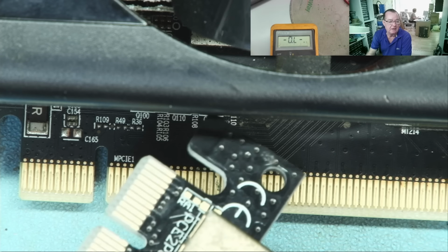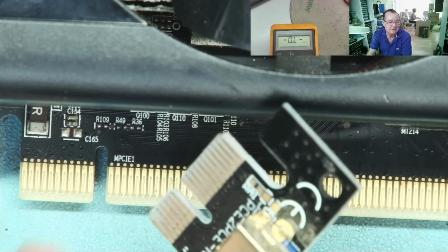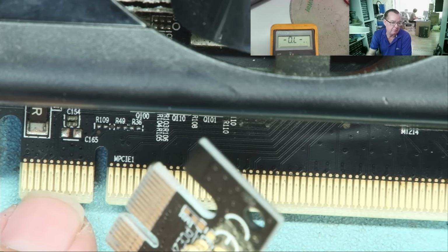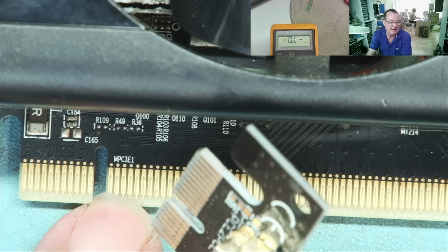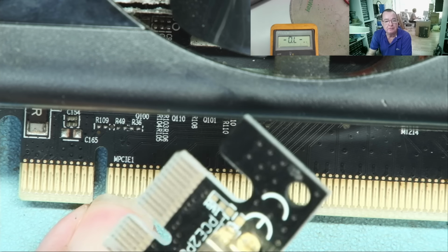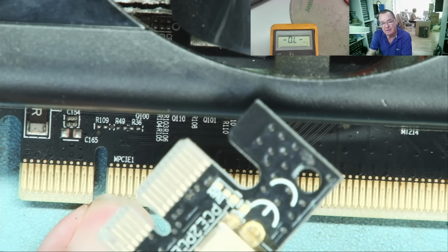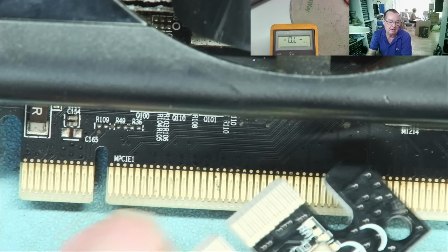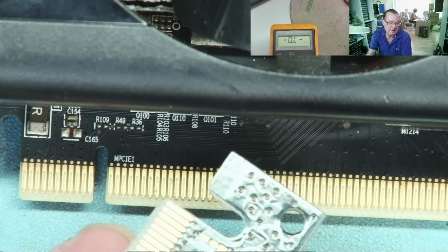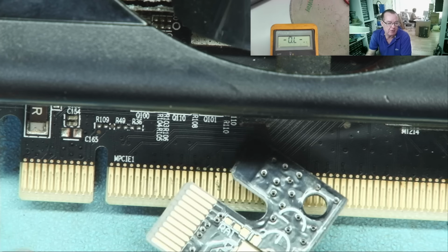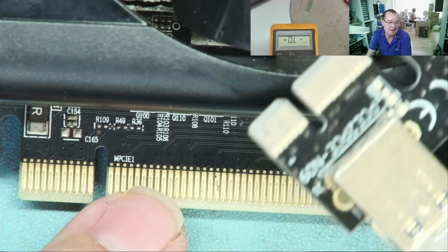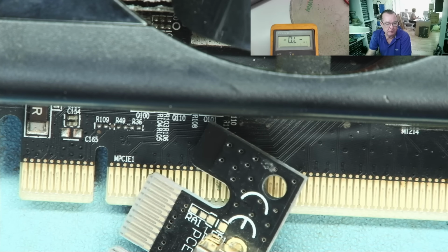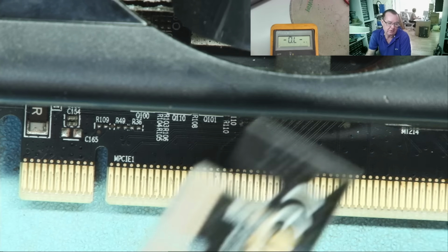So if you do that with one of these things, what actually happens is you connect the first PCIe lane to some of the power rails on here, the 3.3 volts. Now, PCI Express, often called PEX, you'll hear me say PEX. That is the voltage rail that powers this PCIe interface, and it's about 0.9 of a volt. So these tracks go directly into the GPU, and they don't expect to have more than 0.9 of a volt on them. If they have more than 0.9 of a volt, it just kills the GPU.